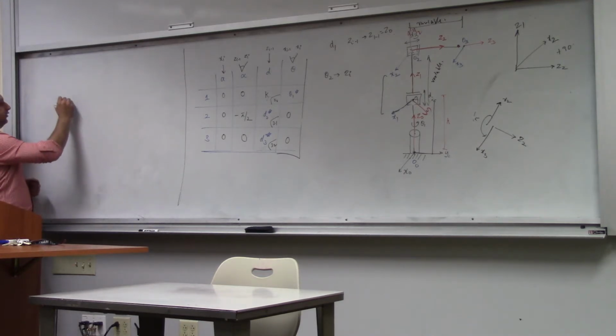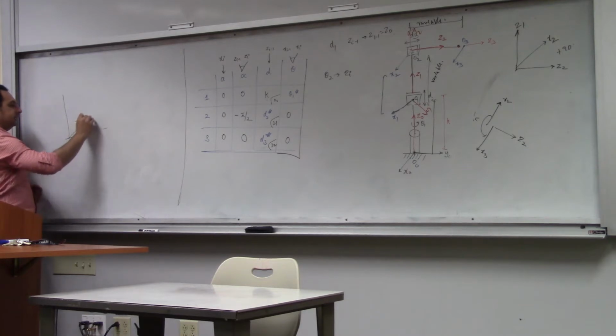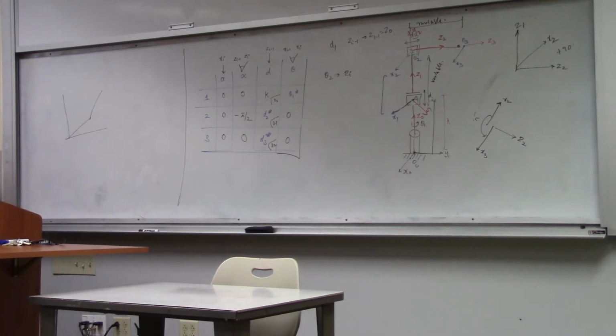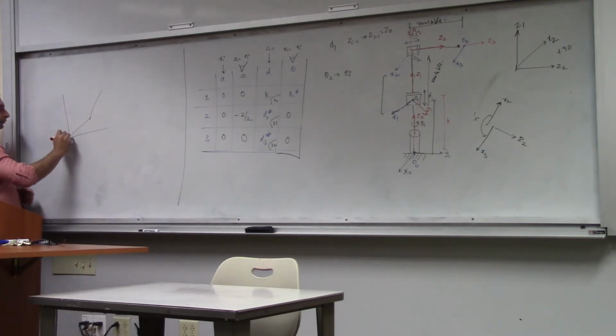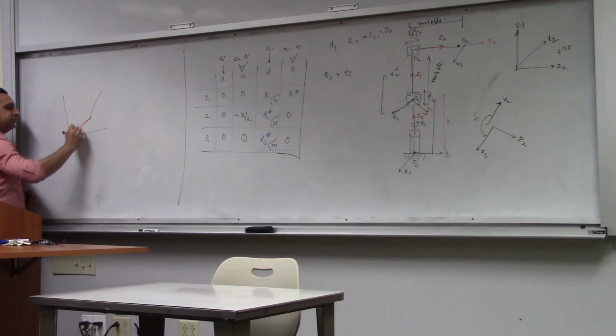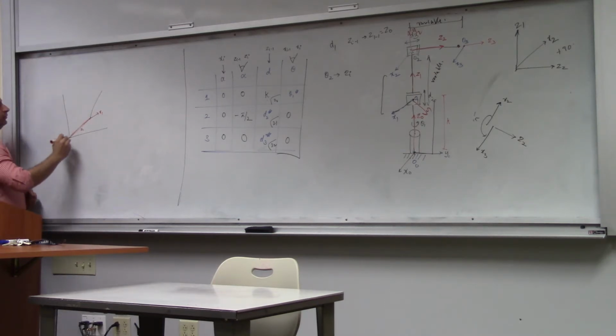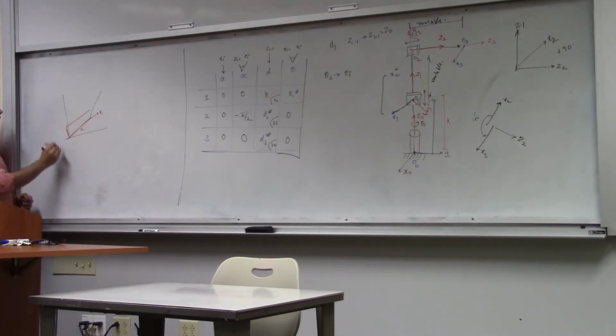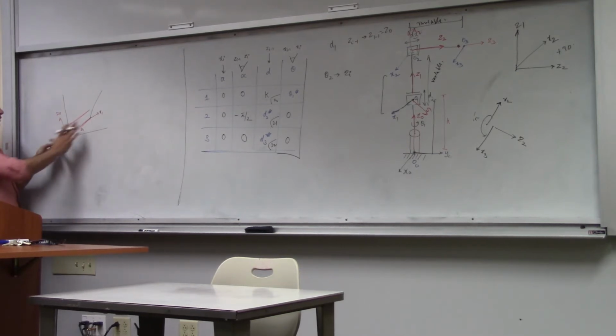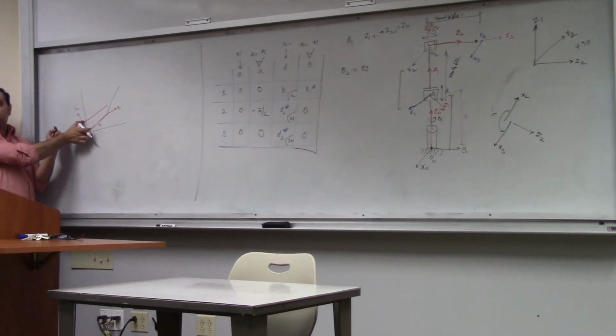So let's say that you had a case where we had a link like this, right? This was the first method. Instead of this, if I have a link like this, this is measured as a, because this is the distance along x1, okay? Sometimes you'll have a link which is like this. So you measure, this will be d along z0, this will be d1, okay? Because these are perpendicular axes, right? So this will be the link length, this will be the link offset, okay?